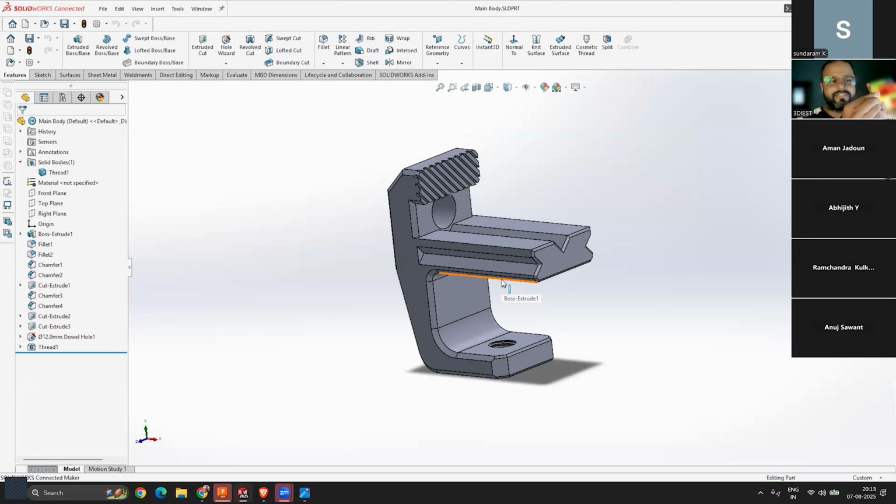So if I just take this corner piece of this Rubik's cube and design that in SolidWorks, that will act as a part file. But once we take multiple part files and show an assembly like this inside SolidWorks, that will be known as a SolidWorks assembly file, right? And when we want to show someone how the parts will fit together, in which orientation the parts will fit together, in that case we always have to show the SolidWorks assembly. So this is the basic difference.